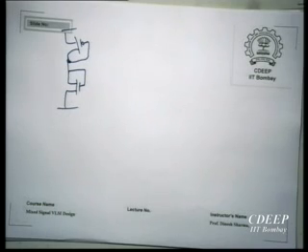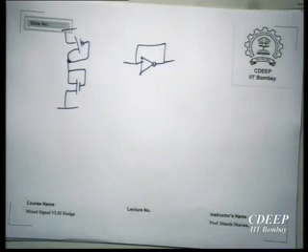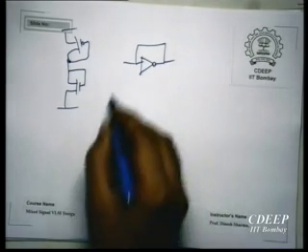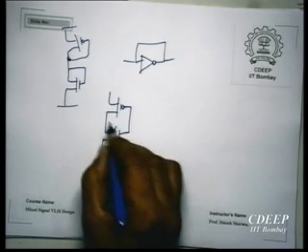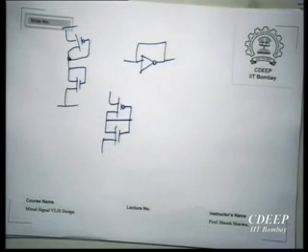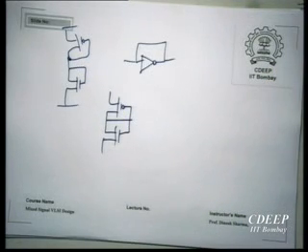Okay, so you rub your eyes and look at it again. What circuit is this? This is just a shorted inverter. Right, because this is the circuit. So this is just a shorted inverter. Therefore where will it settle? To the trip point close to VDD by 2, but whatever is the trip point of the inverter. Okay, and that's good, because now for the amplifier we can use another matched inverter, and it ensures that the resting voltage here is close to the trip point of the second inverter, right?